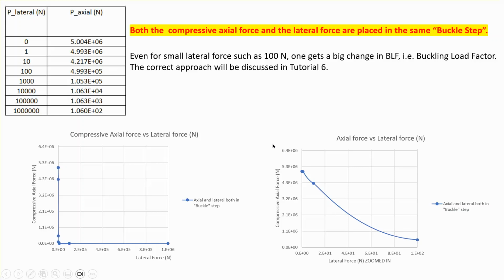Okay, good. But anyway, the point is that when you look at it, this is for 0 lateral load, which means the original buckling load. And then when you make the lateral load 1 Newton, well, the buckling load is very close to it. And when you make it 10, well, it's okay. It's not 499 or 5. It's almost 4.3. It's this line. It's 10. And then when you go to 100, it's about 100. So this number is not right. This should be 1 or something.